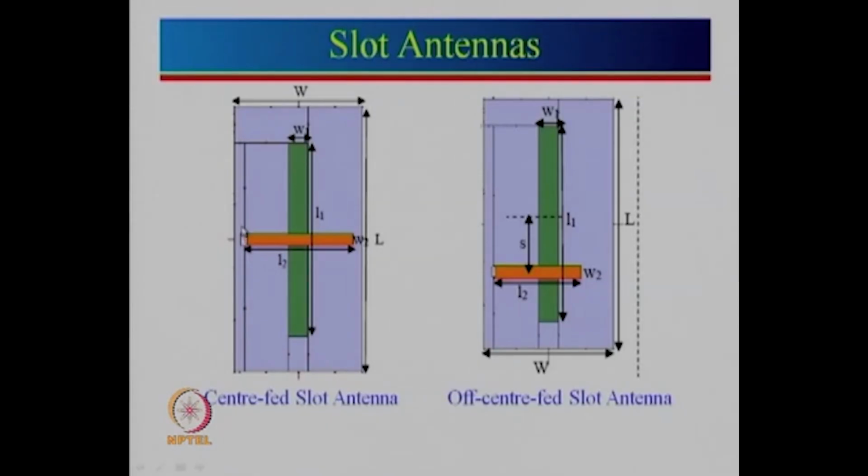So what is a microstrip line? Actually speaking, it is a line which is printed on, let us say, a PCB, printed circuit board. So on one side we have a ground plane with this particular slot, and on the other side we put this feed, and here we are feeding the antenna. So this current flows through over here. It actually sees an open circuit here. So current will be maxima here if this length is approximately lambda by 2. So the current is maxima here, that means the magnetic field will be around that, and that magnetic field gets coupled to the slot antenna.